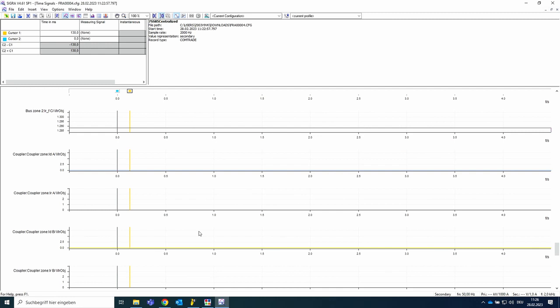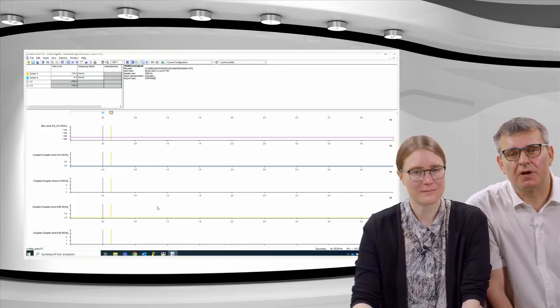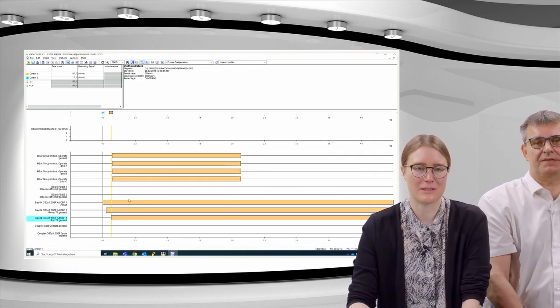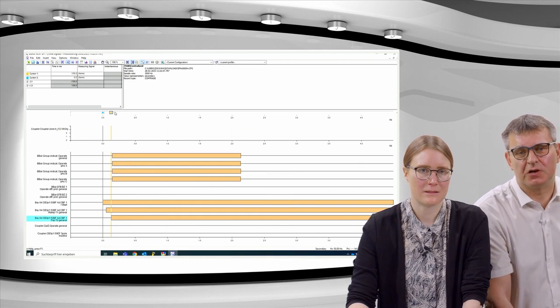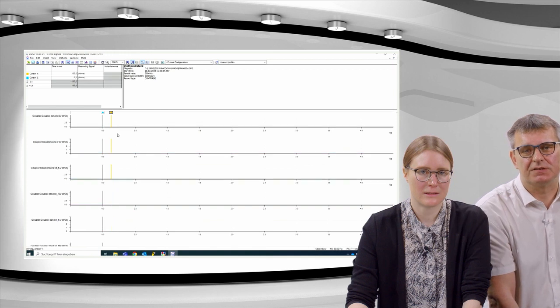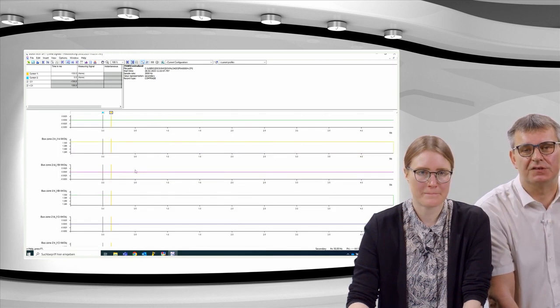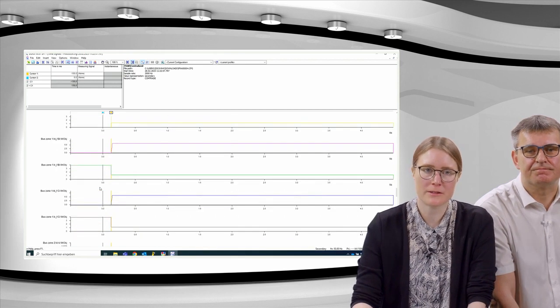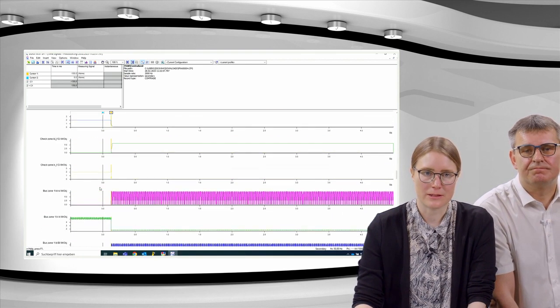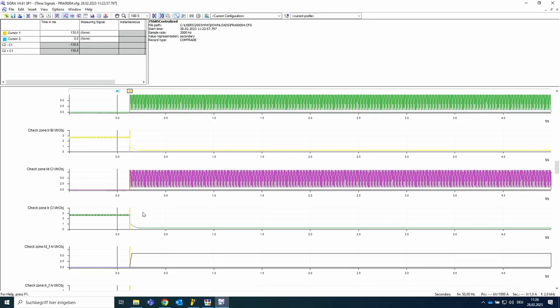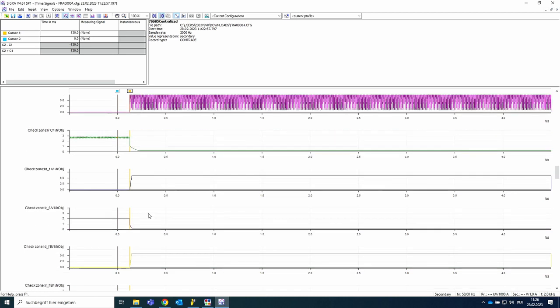Once again, before we go to the differential current, do you have now the yellow cursor on the trip T2? The yellow cursor, yes, okay, exactly, fine, because the trip T2 now will stimulate the unbalancing of the bay current. And so let's see how the timing is. Okay, bus zone 1 was the one that was relevant for this fault. So let me just scroll to the bus zone 1.